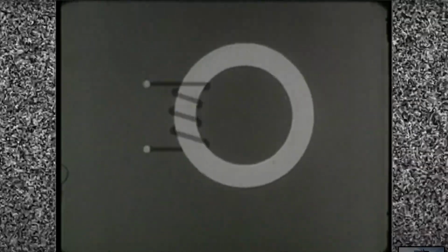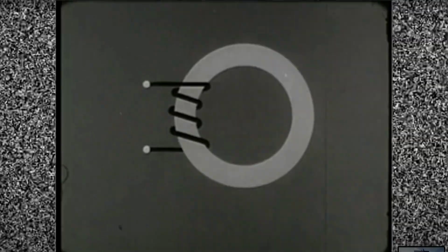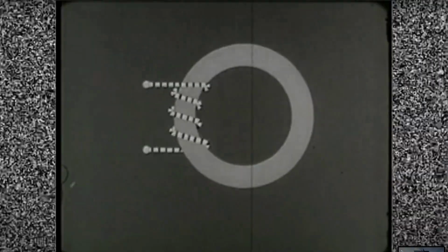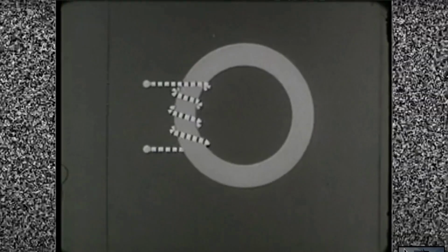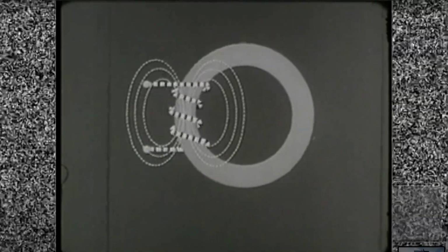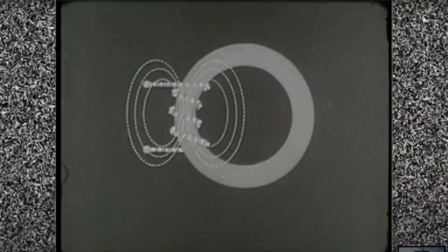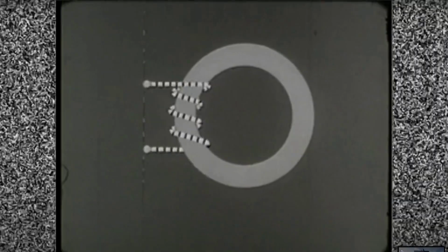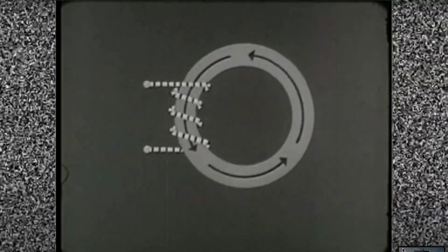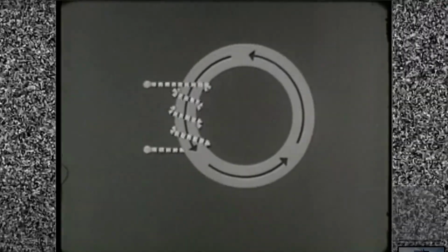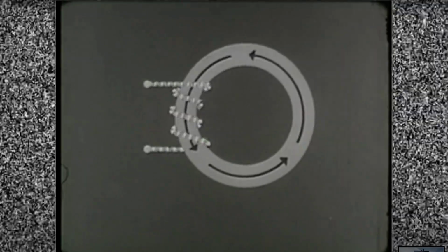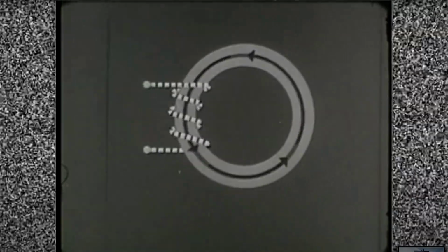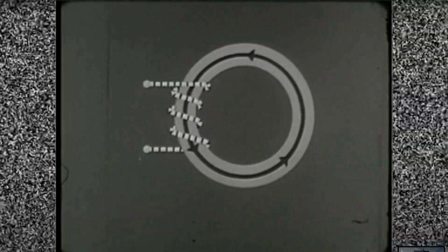To explain how cores store binary digits, we must know how they are constructed. Around the core is wrapped a conductor. Current flowing through the winding produces a magnetic field around the conductor. Because the core is made of highly permeable material, it forms a path for the magnetic lines of force. Because it is ring-shaped, the path it forms is a closed loop.